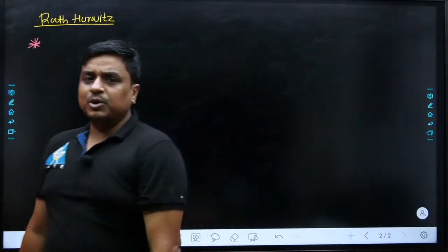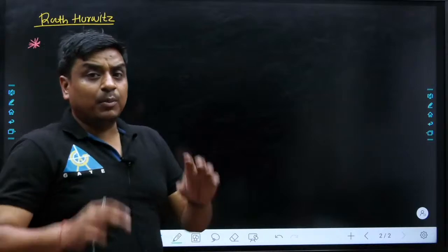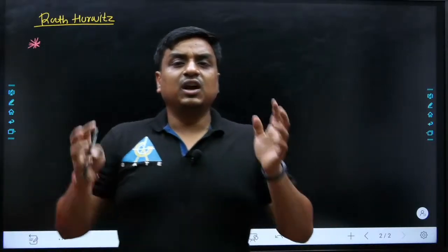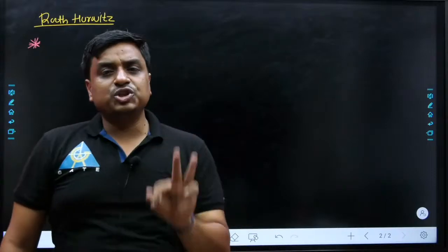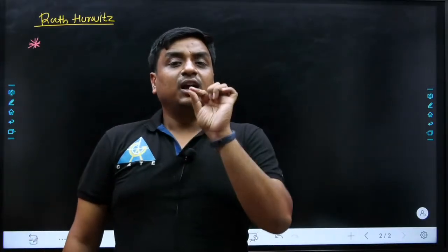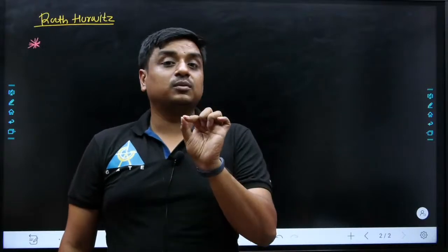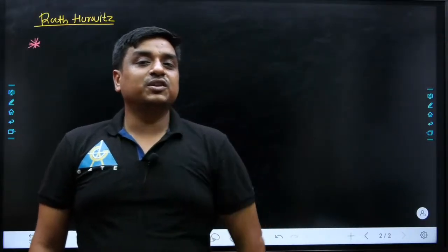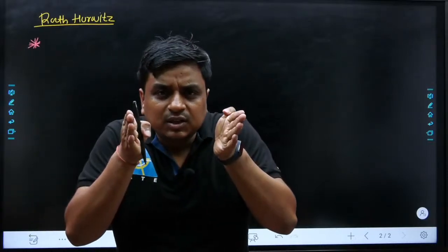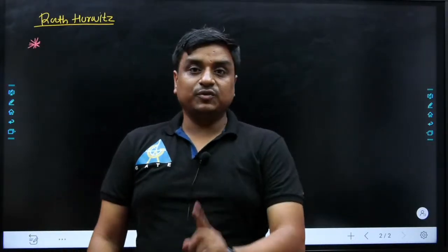If you can recall, about 3 to 4 days back I was discussing the different components of the transfer function. We got to know the transfer function has 3 different components, starting from zeros, going to poles, and similarly DC gain. So which factor was responsible for the stability, or the pure stability, of the system? It was nothing but the roots of the denominator, or the locations of the poles.